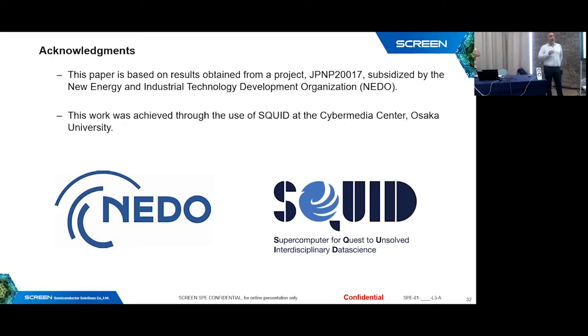That's why at the beginning we put RANS, because we wanted high accuracy simulation, okay? And we didn't care about the turbulence. Because for us, our system, but this is what we thought. When you do the calculation, the Reynolds number is low, so why should we go to LES? But in reality, RANS is not working. We have to do LES, so we have some turbulence, and it's mostly at the edge of the wafer.